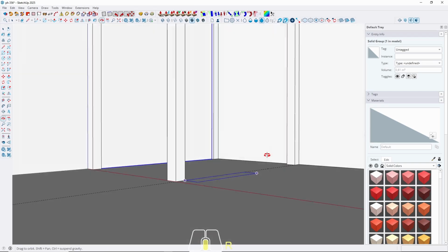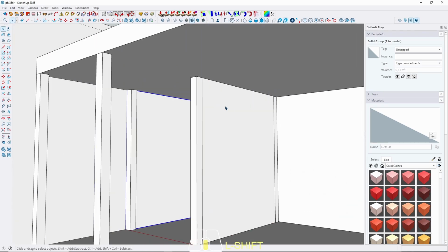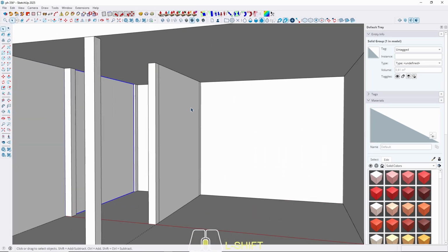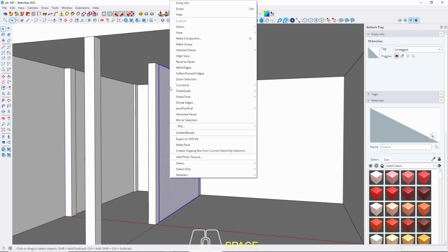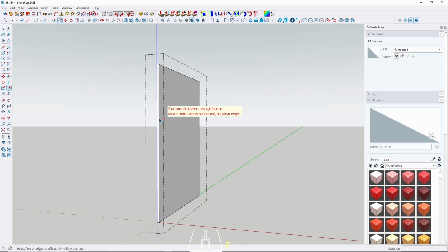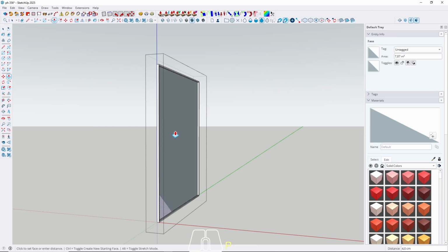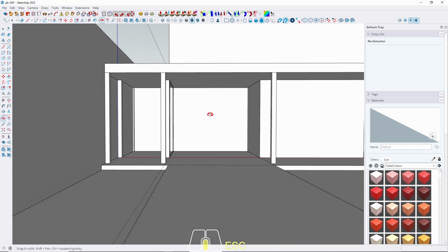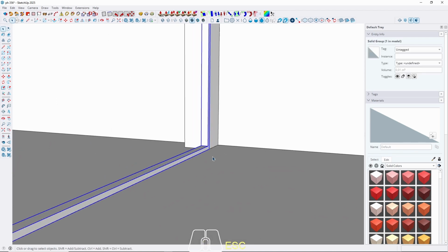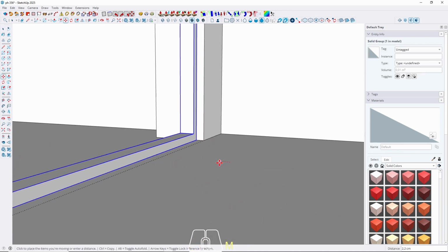Let's make a frame. I want to make the frame very sleek, so I think 4 centimeter is enough. And then the depth, it's only 2 centimeter. Okay, very sleek design. And push it 2 centimeter.